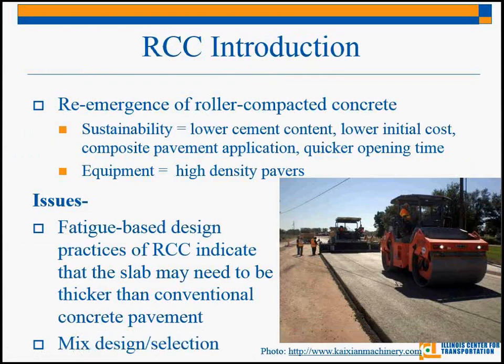So why are we interested in this? Well, recently it has become more relevant as we push for sustainability. I'm sure you've all heard of this because it's basically the reason we all have jobs, well, at least most of us. RCC is good for sustainability because it typically has a low cement content. Cement has the highest cost of most of the constituents of concrete, and it has the most emissions to make.